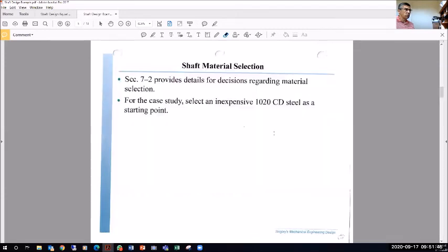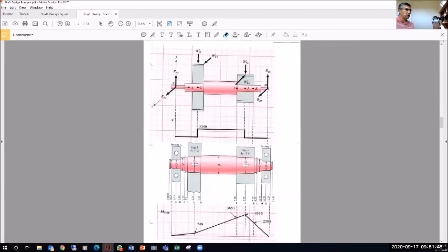So if I show you quickly where M is, again, I'm always referencing this chart. So now we are looking at point M right here. This is the shoulder where the bearing sits. I'm going to have to use a sharp fillet radius because the bearing is leaning on this shoulder, unlike this shoulder where we had used a general fillet radius.